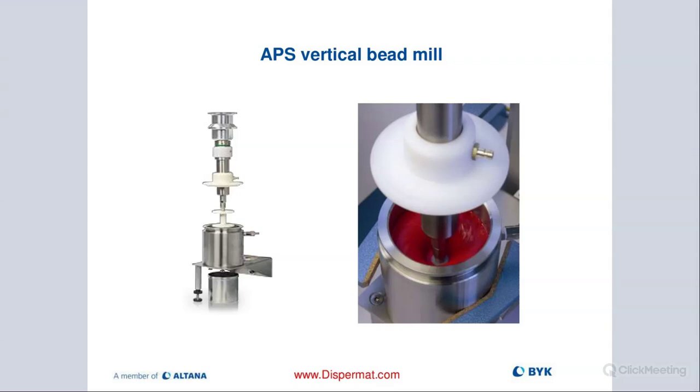In this case, we have a double milling impeller, and turn the whole thing into a medium mill. You would also at that point add the beads to the container on top that has the mill base, and then you push down that cover that you can see here on the right with an air socket right on top of that cover.